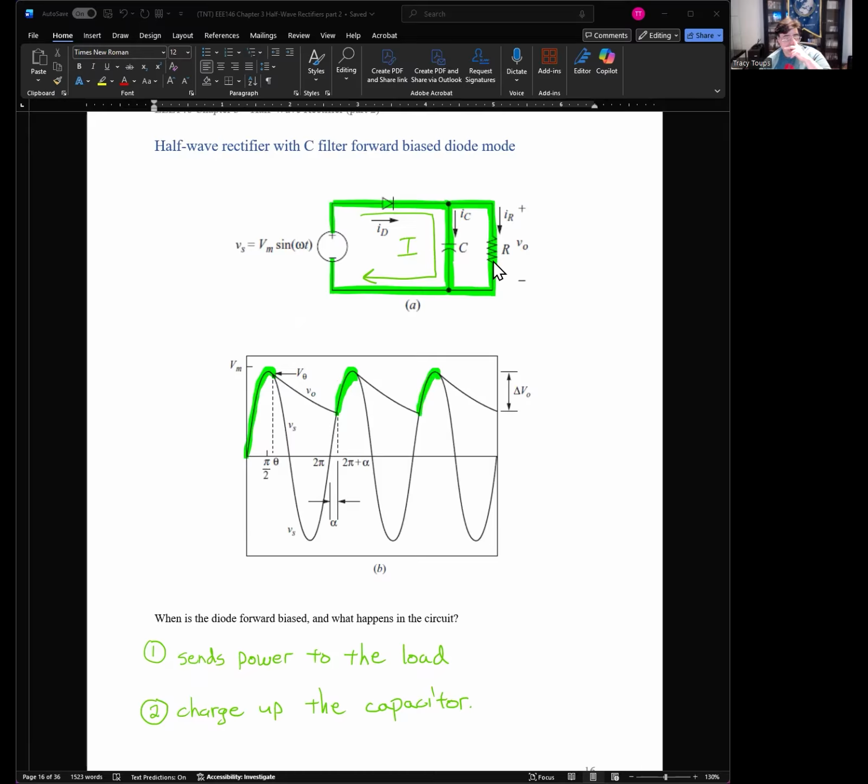So that's the big thing: when the capacitor isn't holding up the voltage, it's taking in the current. It's absorbing energy. So right here in this green line, the capacitor is absorbing energy. Then right here, it releases it, but then the AC waveform comes back and it absorbs it as well. So this source does double duty of not only sending energy to the resistor, it also has to send energy to the capacitor, so the capacitor can work whenever there's no source connected.